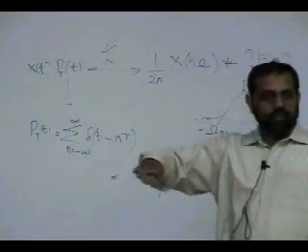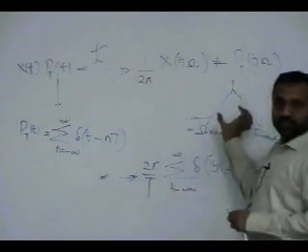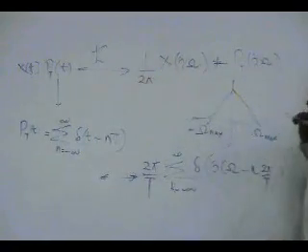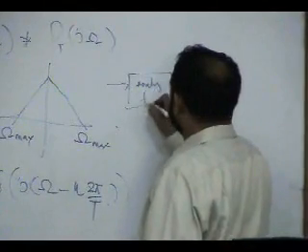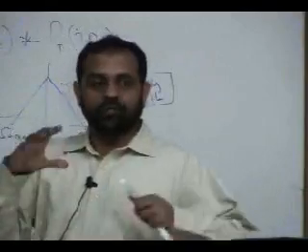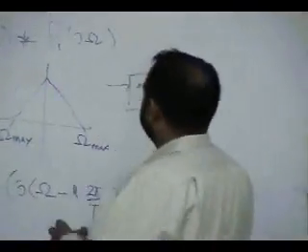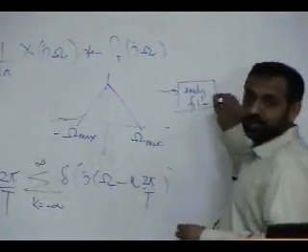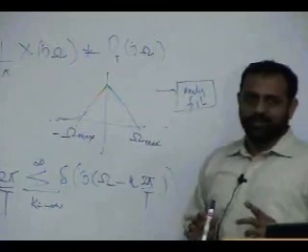So the signal basically mainly concentrates in these frequencies, and usually with every A to D converter you put a continuous domain analog filter. You put an analog filter to make sure that the unwanted band is down. So with every A to D converter you must put an analog filter to clean the spectrum, otherwise sampling will corrupt.